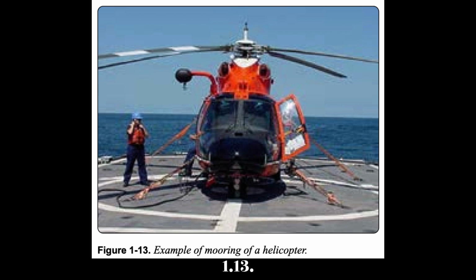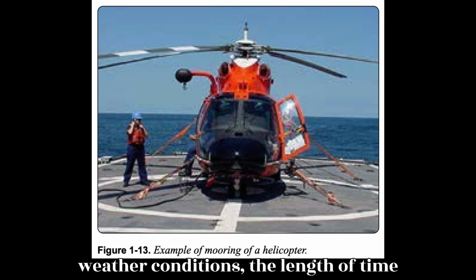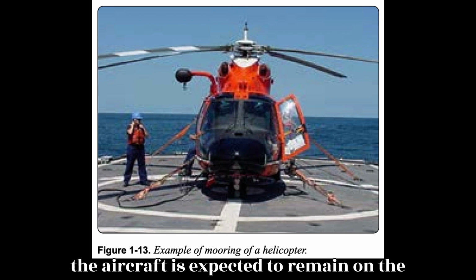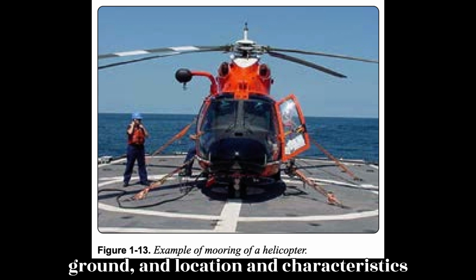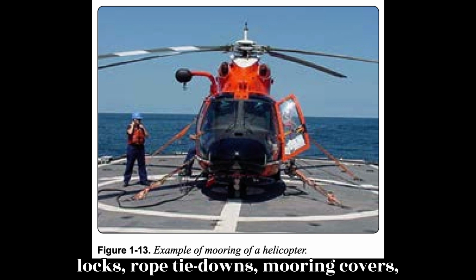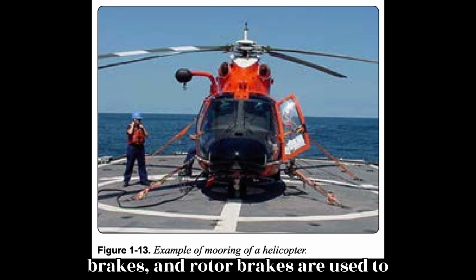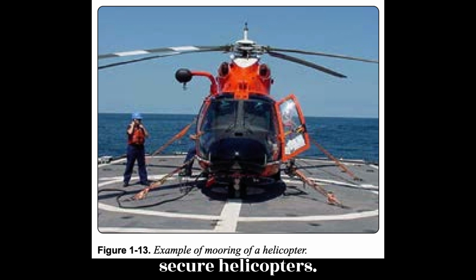Figure 1.13. Methods of securing helicopters vary with weather conditions, the length of time the aircraft is expected to remain on the ground, and location and characteristics of the aircraft. Wheel chocks, control locks, rope tie-downs, mooring covers, tip socks, tie-down assemblies, parking brakes, and rotor brakes are used to secure helicopters. End of page 1-10.